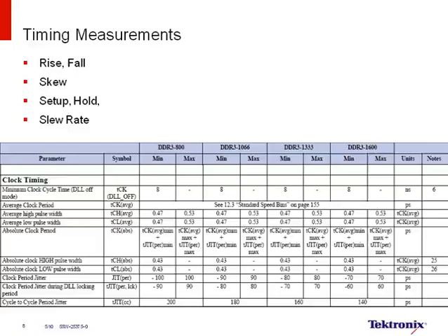Skew, setup, and hold measurements are critical in any digital systems that use clock and data. In the diagram you see over here, this is an excerpt from the JEDEC DDR spec, where there are massively parallel clock strobe and data lines.